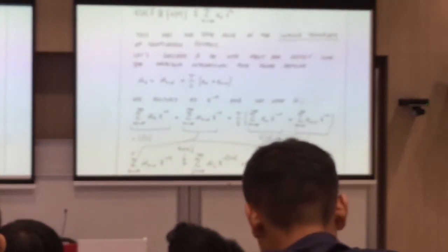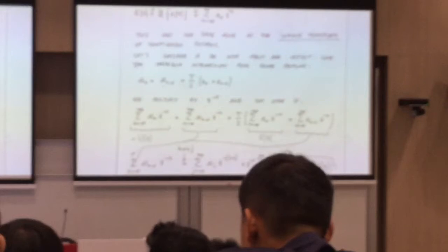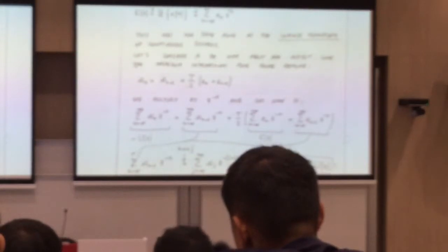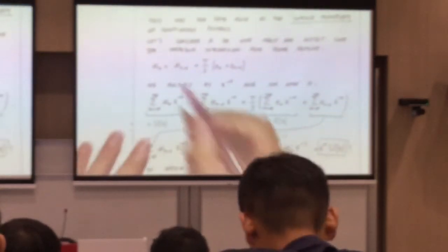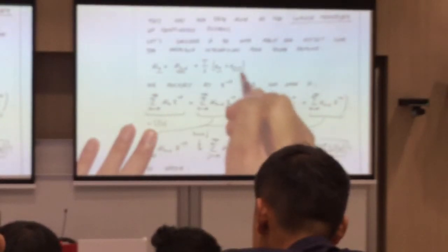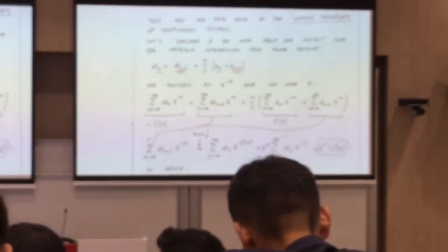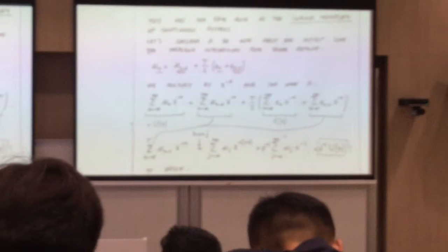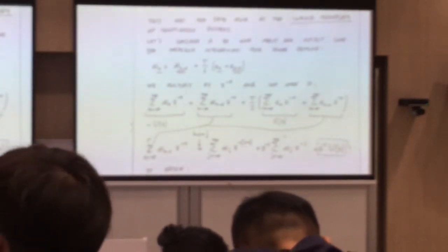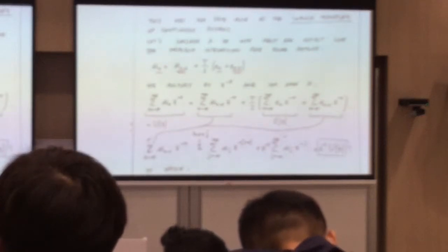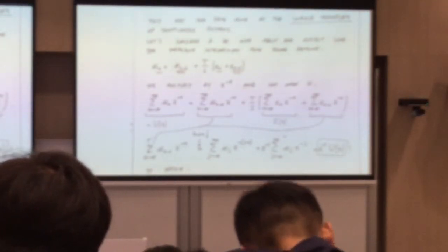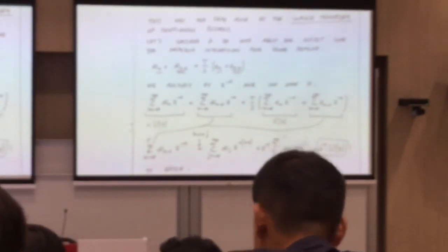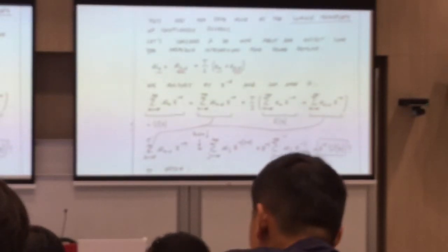So what we can do is, once you get the difference equation, you can do the Z transform. After you get the Z transform, then you are able to convert your time delay. For example, here you see you have a time delay, you have k, you have k minus 1. Right? For more complicated ones, you can use k minus 2, k minus 3, k minus n. So if you have n delays, you will have n variables. Then it may be very difficult for you to visualize and very difficult to do analysis. Right? Because you have so many independent variables. But after you have done the Z transform, how many variables do you have?